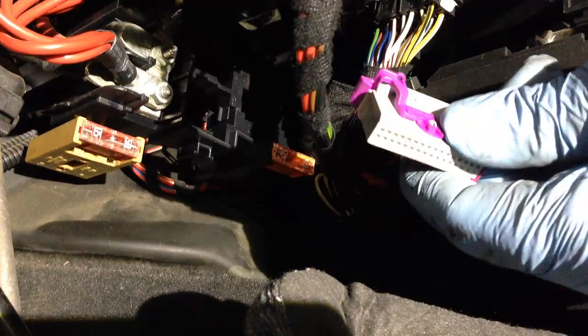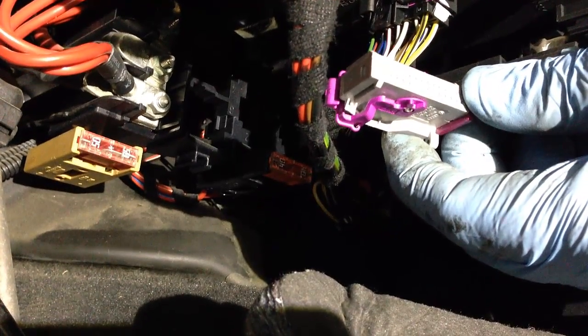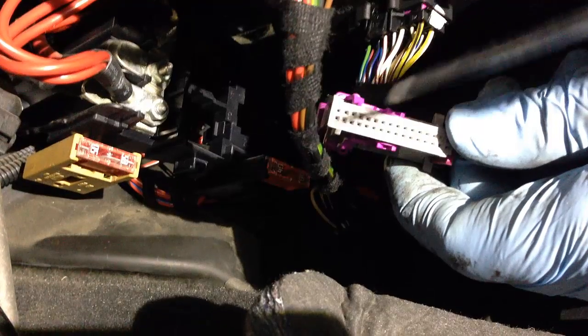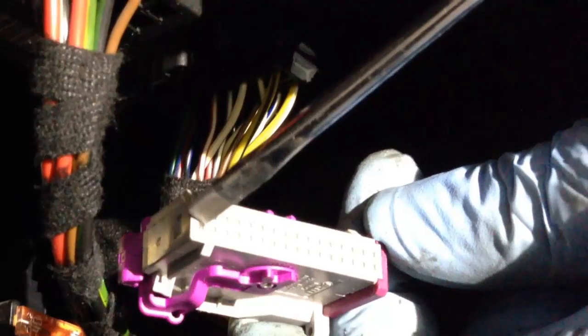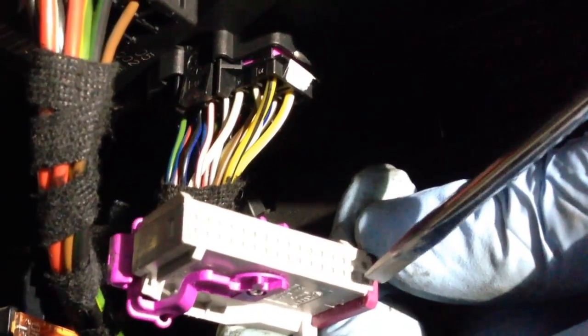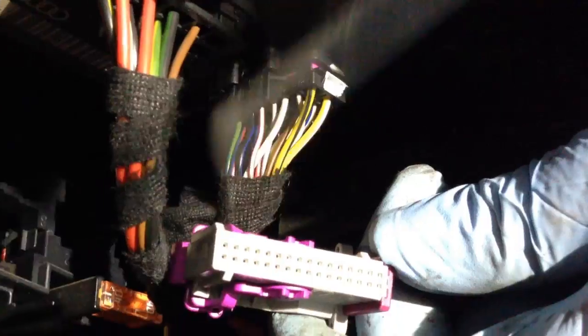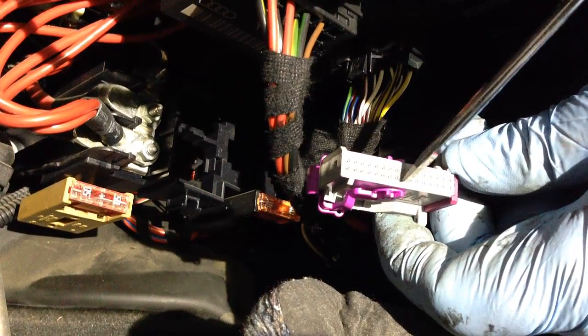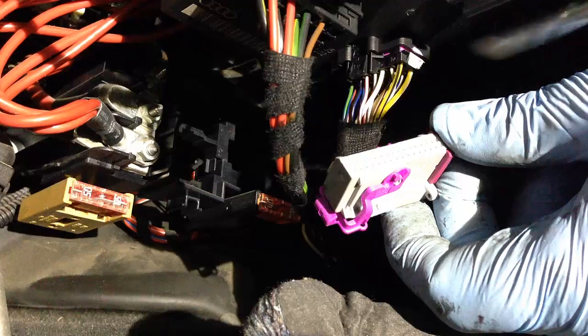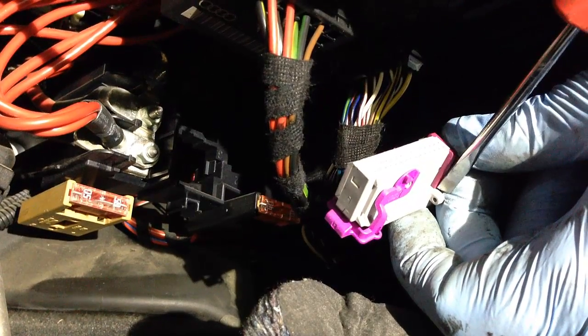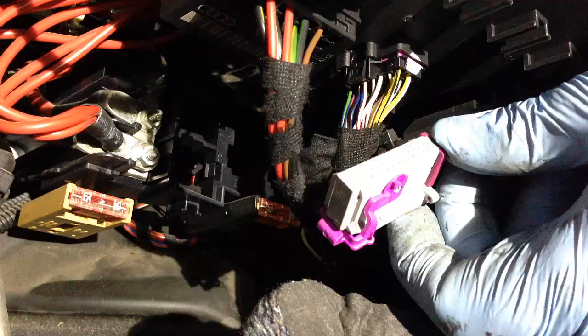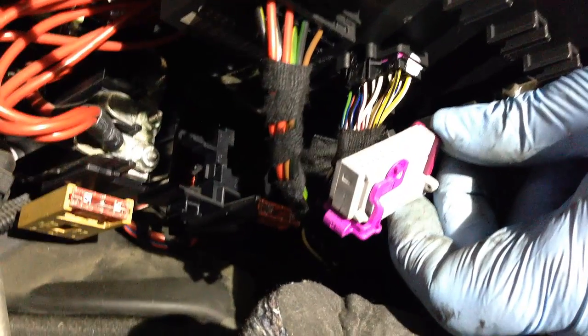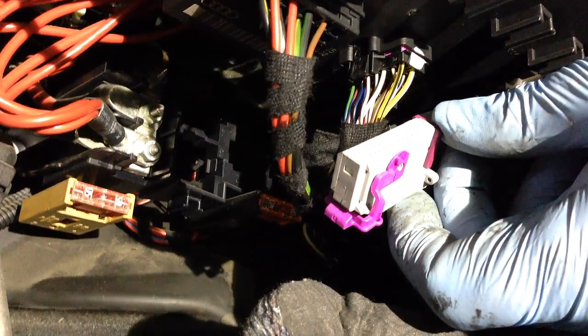Okay, so there we can see our connector. What we know about this connector is that we have very small etched pin numbers, and that looks like 1 to 16 and then 17 to 32. So we've got 2 rows of pins on there. We're looking at the diagram pins 12 and 13, which will be along this side somewhere. So what we need to do is strip this connector out, pull this bracket off here, and then the interior of the connector will slide out, and then we'll dive in there with our scope and have a quick look and see if we can see what's going on. And we'll see you in a second.